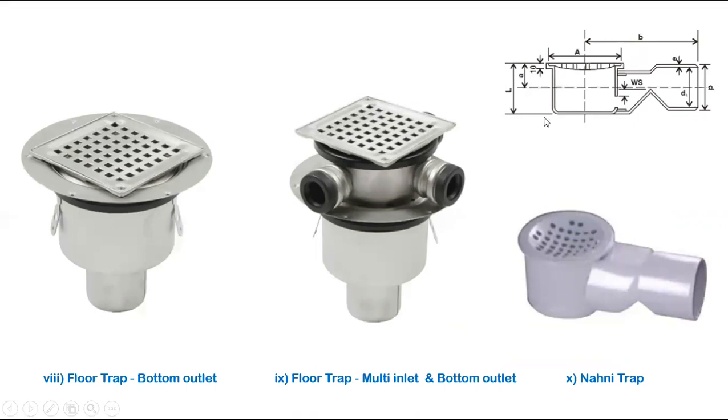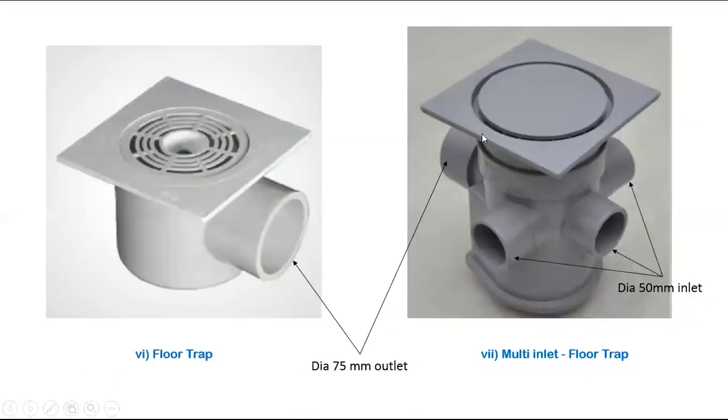You see, here also, this multi-inlet fixture you have to install, means you have to provide it on the second floor or ground floor. Ground floor means you will get the full soil. Top floor means you have to provide a sunken slab. Only one sign: sunken.